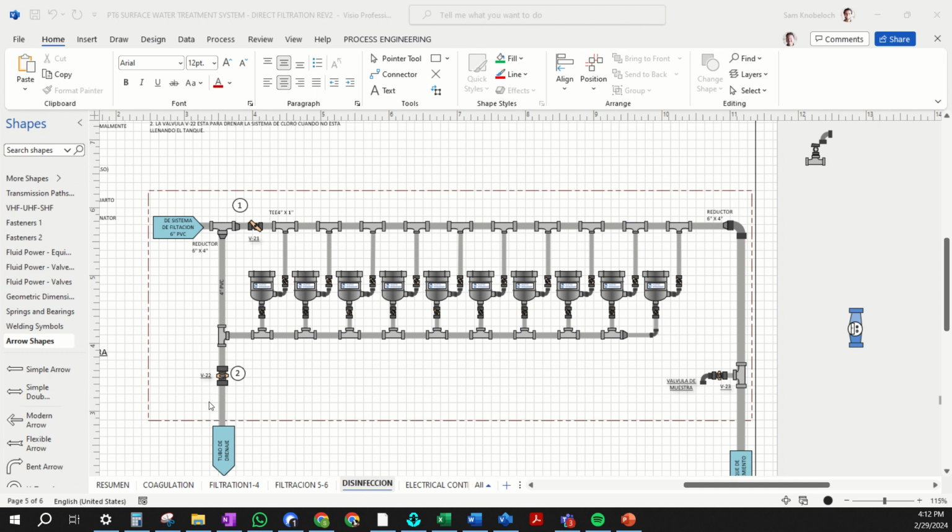You have the pipe coming in, the bypass line at the top, the chlorination line at the bottom, and the water should go into each of these chlorinators evenly. Then join with the bypass line and go that way. So we're going to model the same way. Of course, we're only going to have 3 chlorinators in our model, but it's going to look like this.